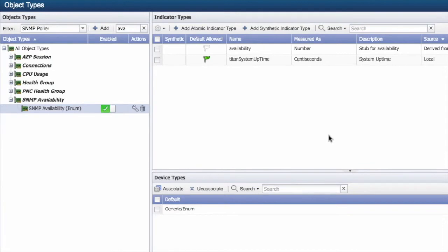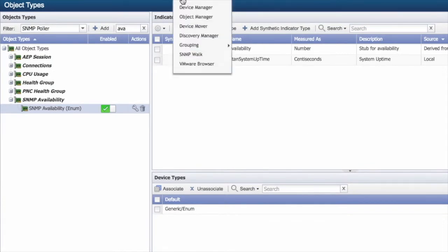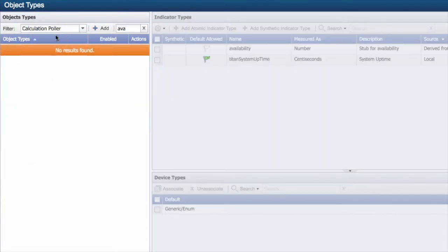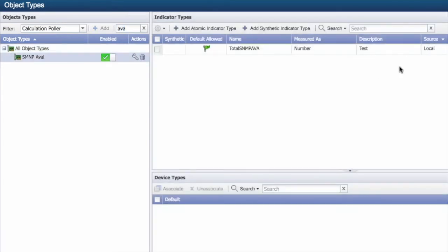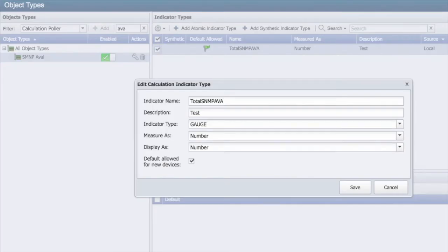If we had classified it incorrectly, all we have to do is go back up to our filter tool, calculations, select it, and then click the wrench icon on the right hand side, and you'd very easily be able to change it as if we started new.